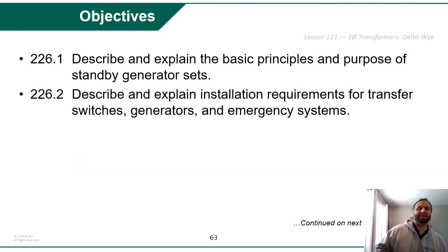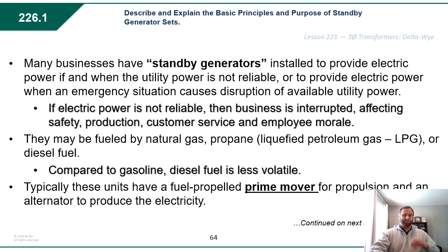226. Describe and explain the basic principles and purpose of standby generator sets. We're going to talk about standby systems, whether they're required, whether they're optional. Explain the installation, looking up the NEC references for them. Many businesses have standby generators installed to provide electric power if and when the utility power is not reliable, or to provide electric power when an emergency situation causes disruption of available utility power.